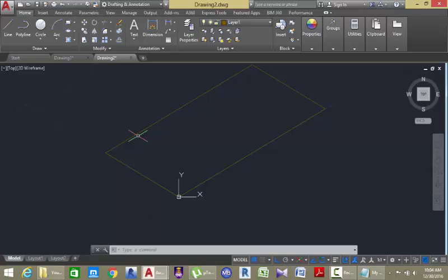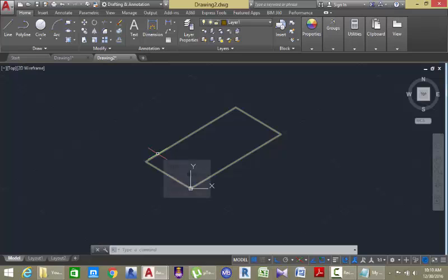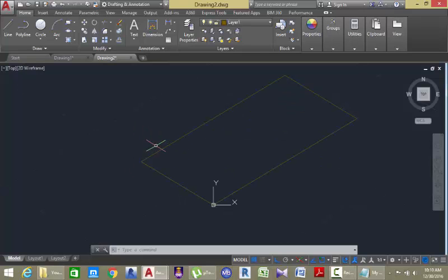Now let's draw the frame of our table. We want the top of the table to extend 2 inches from the frame, the support of the table. Now we need to draw the 2 inches from the origin, from the first rectangle, the edge of the table. But in this type of drawing, I don't recommend using the offset command. I will show you the reason why I think that is not a good option for isometric, especially when you want a distance like this one.